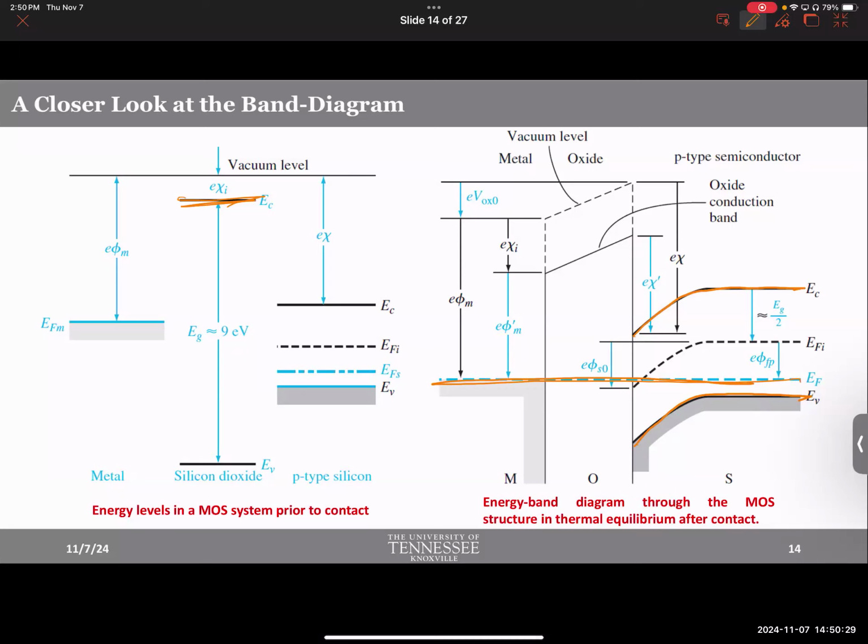I showed you, you do a double derivative, use Gauss's law, and you can basically understand the shape of the band diagram by going through that math. We could always derive it mathematically, but we are not going to derive it for every band diagram we draw, right? So it's much easier to understand or remember it using a trick. But deeper down, you should understand that this is all related to energy minimization eventually.